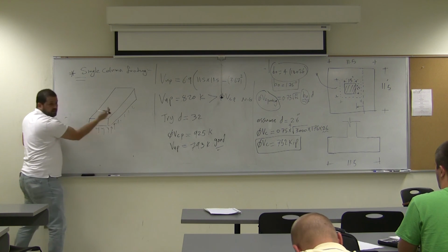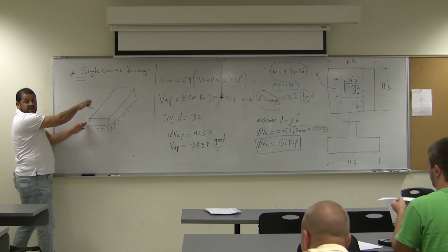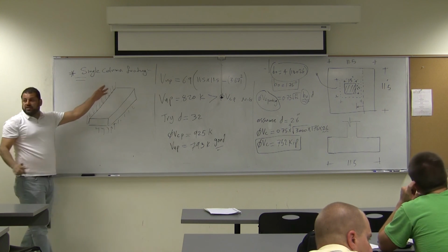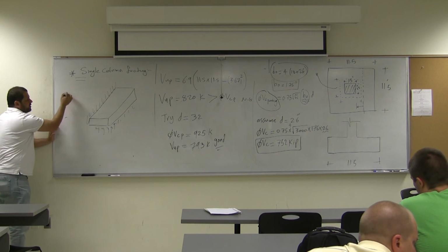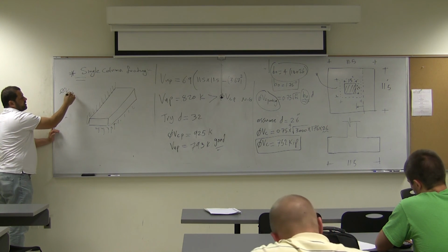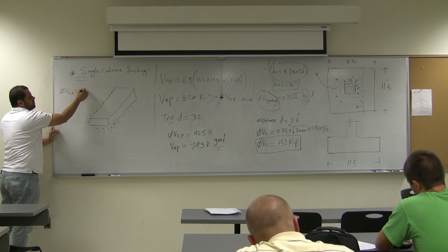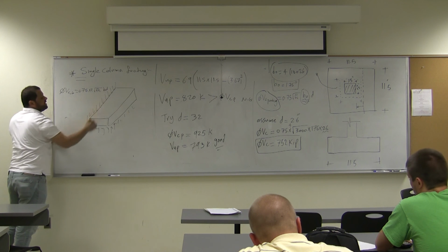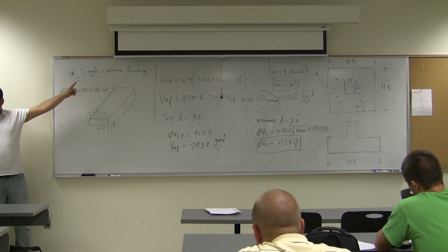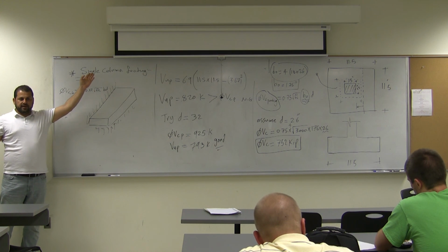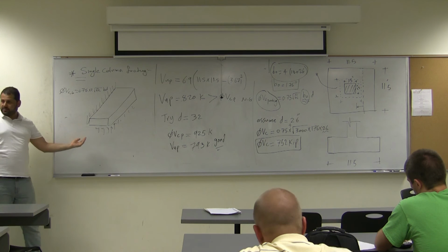So the pressure is all under. So this side here, from the inside, will have the beam shear strength, which is this side. The beam shear strength is what? Phi Vc, beam shear, equal what? That's the old one: 1.75 times 2 square root of f'c b d. Not b naught, bd. This is the classical one. We took it in beam design. Okay? So this one must be compared with what?